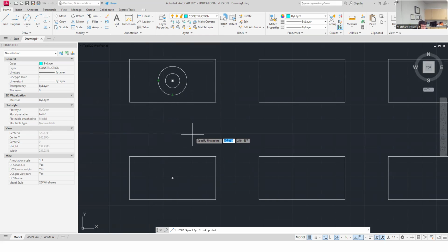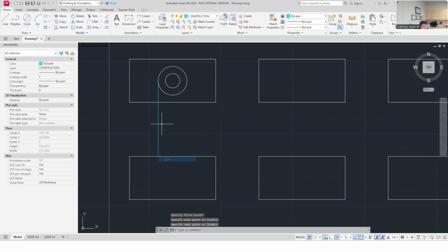That makes sense. We call that the rectangular view of the circle. And so how I actually get that is I come out here to the outermost tangent edge, which quadrants are a great snap to have on for this. And I want to project this down to my block. Keep a nice parallel 90. You can use ortho mode if you want to. I just make sure that I have this one right here on. I make sure that my snap tracking is on.